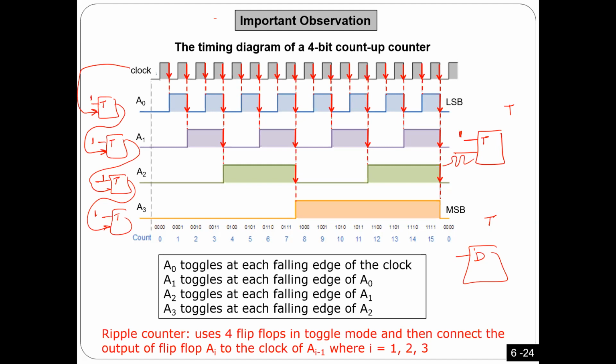Anyone can tell me? You have something to say? No, I'm going to make it easier. Look here. I have Q and I have Q prime. I'm going to connect Q prime to D. This is the output and this is the inverse of the output, so if this is 1, this is 0. I connect this one to here, and that's how I can make it toggle. So every clock, this one is going to toggle.